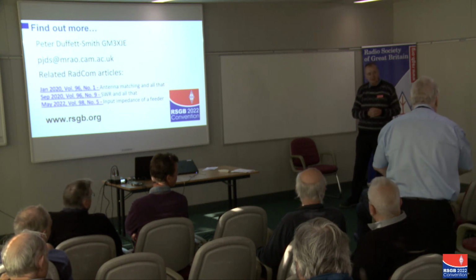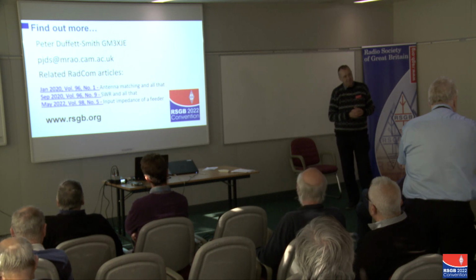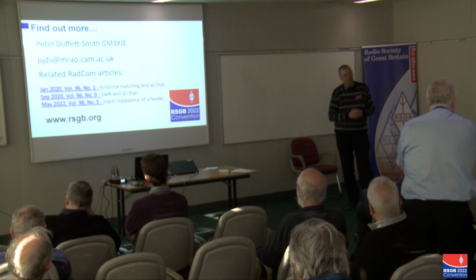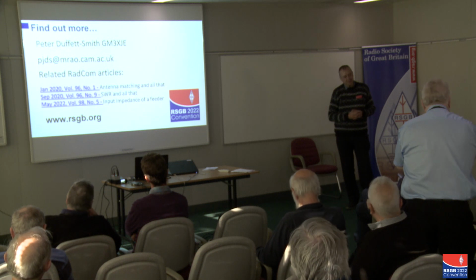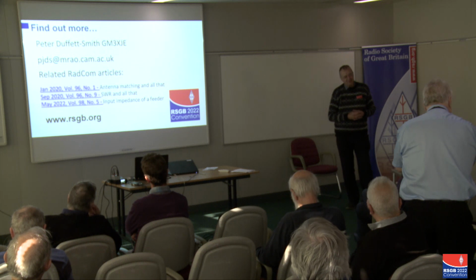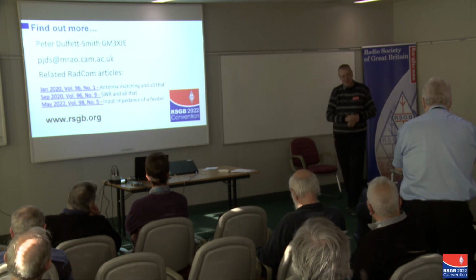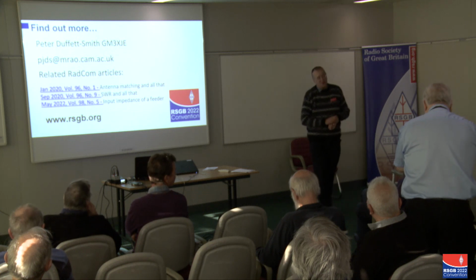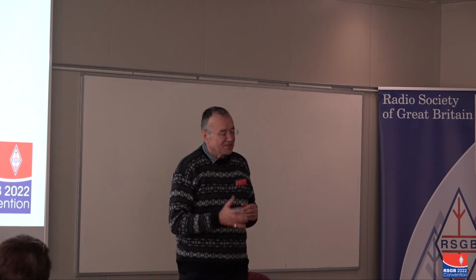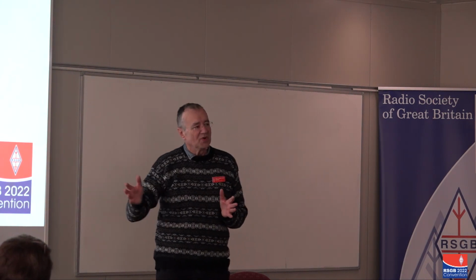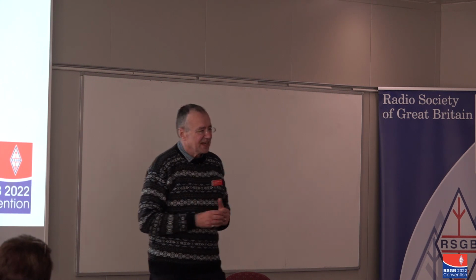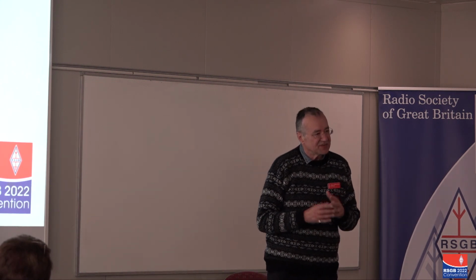Yeah, good morning. I just wanted to pick you up on, you said right at the very beginning that power is only absorbed in the resistance. Yes. Then you went on to say that you start with the transmitter bunging power into the coax. It's always a confusion when people say that. That's a very good question. What one has to remember is that when we're talking about these things, we're always talking about the steady state condition. When you start, there is a time before the steady state condition is reached. It will be microseconds, but nevertheless there will be a time.